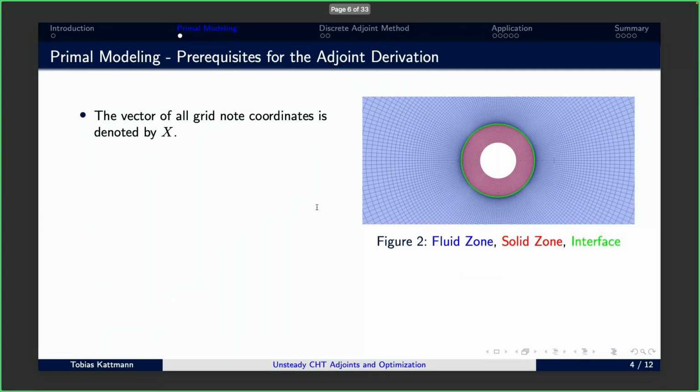And to set the nomenclature, unfortunately, I'm not able to showcase in the application this heat exchanger I was showing before. I have to resort to the most simple case, which is a 2D pin in crossflow. So a very simple mesh to start with, like 22K or 28K if you take both zones, cells. So a pretty small case.